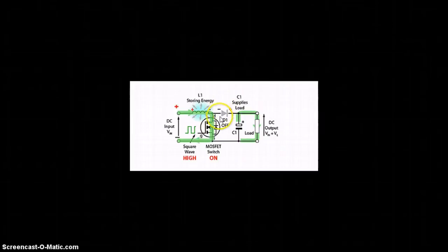Now again during the positive half cycle, the MOSFET starts conducting. The diode is in the off state. We can see there is a negative here and positive here as the back EMF, and the charge present on the capacitor, VL plus Vin, is now given to the load.